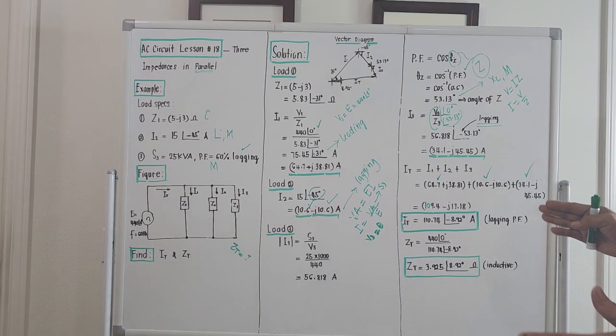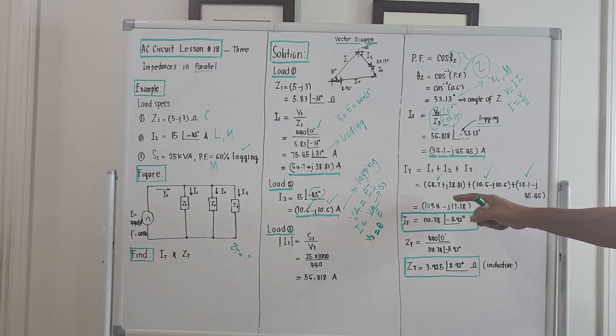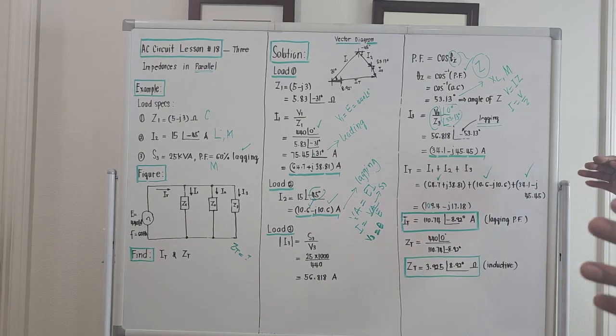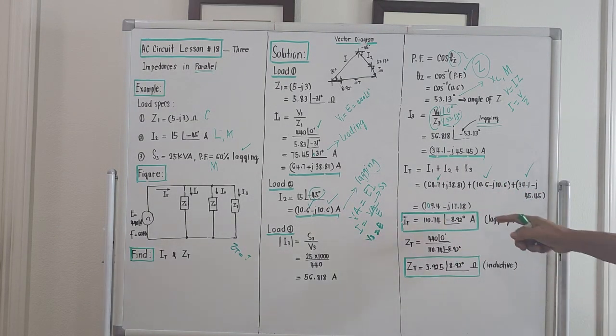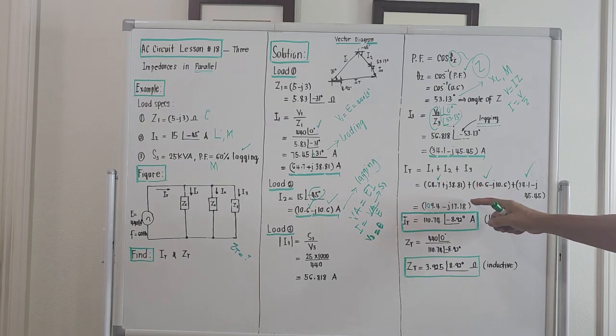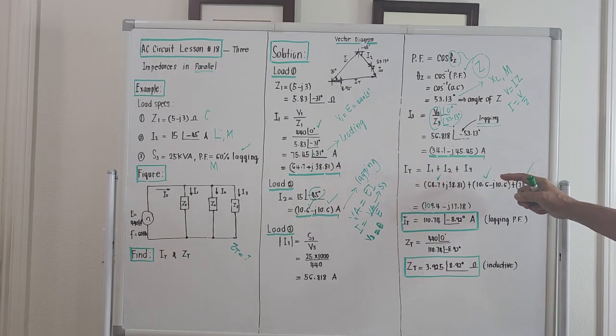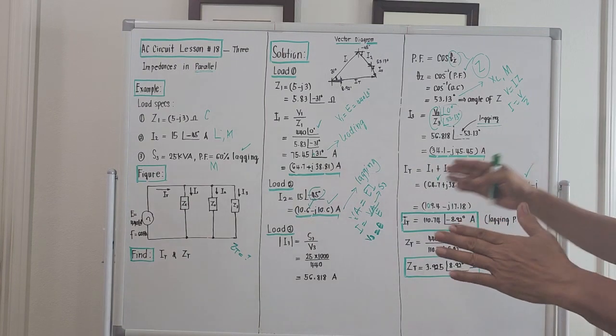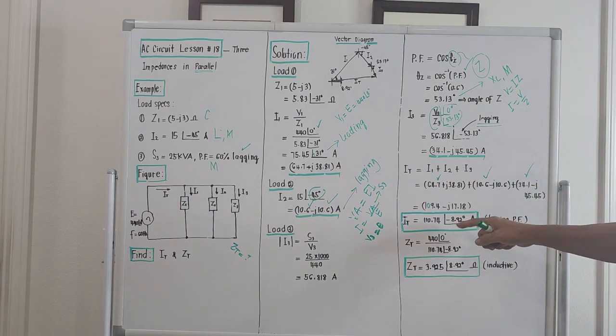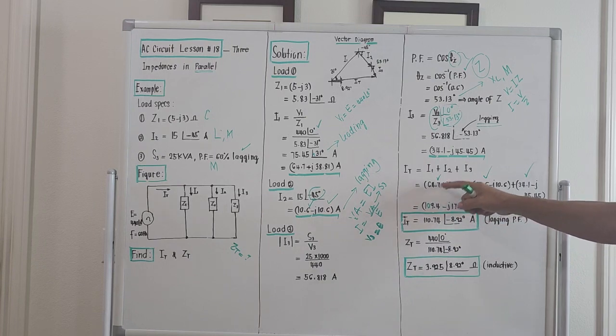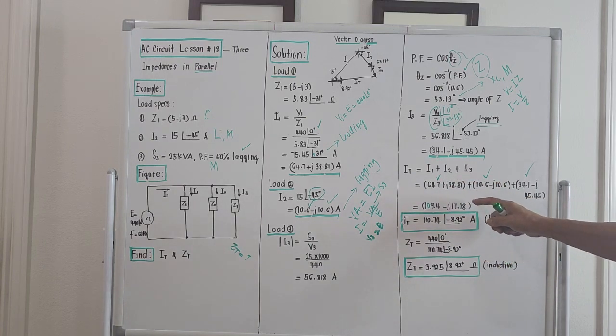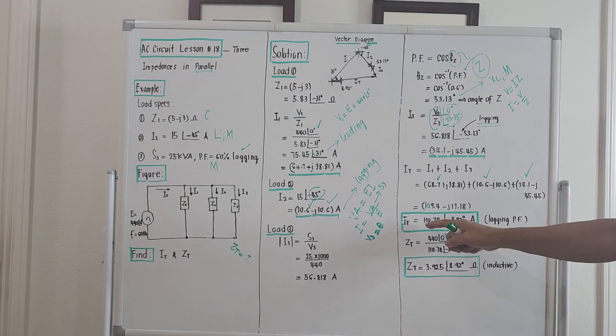And to compute for the magnitude of the total current, we convert this real and imaginary to its magnitude value, right? So you divide 17.18 divided by 109.4, okay? You press arc cosine. The resulting angle will be negative 8.92 degrees. Take the cosine of this, you divide that to 109.4, okay? This is negligible compared to this, so this is 110.74 amperes.